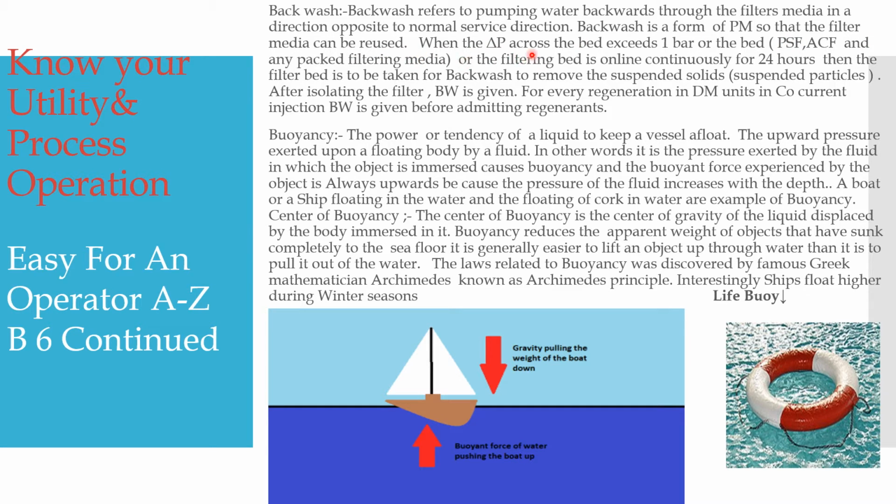So when the delta P across the bed exceeds 1 bar, whether it is precision filter or ACF, or any packed filtering media, or the filtering bed is online continuously for 24 hours, then the filter bed is to be taken for backwash to remove the suspended solids or suspended particles settled over the bed. After isolating the filter, backwash is given.